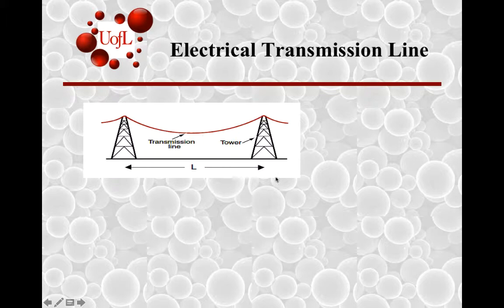Let's say that somehow the length has been specified. Now we have to, from a material side, decide what all this cable can do. What kind of criteria are we looking at? The main criteria we're looking at is, first of all, the electrical conductivity. The other is the kind of strength it can have to not collapse under not only its own weight, but other stresses. What are some kinds of stresses that can be? One can be wind, for instance, right?